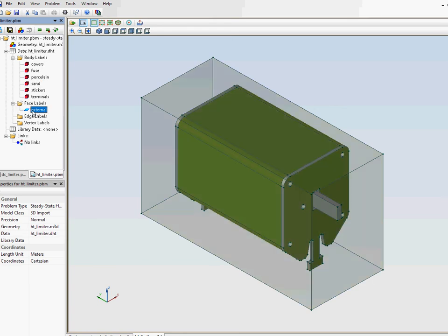So the heat flux coming from inside, from the fuse, will be eventually removed from these faces. And we are interested in the temperature distribution only inside. What is placed outside these boundary conditions is no matter for us. So we have only fuse, sand filling, porcelain case, and boundary condition.